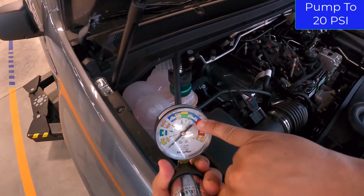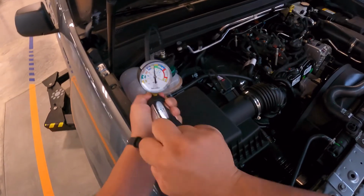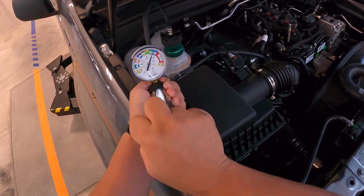From here, you're going to take the pump, pump it to 20 psi, which is what the rating was on the cap. So you're going to go off the gauge on the tester, raise it to 20 psi.